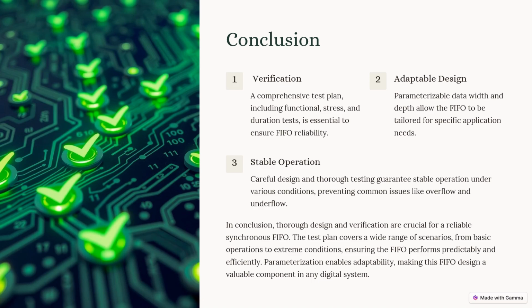This project successfully implements and verifies synchronous FIFO using Verilog, ensuring its correctness through an automated test bench, covering adaptable design with stable operations. The FIFO design efficiently manages sequential data storage and retrieval, making it a critical component in digital systems for buffering and synchronization. The project not only strengthens our understanding of FIFO architecture and test bench automation, but also provides a solid foundation for future enhancements. So that's all from my side.